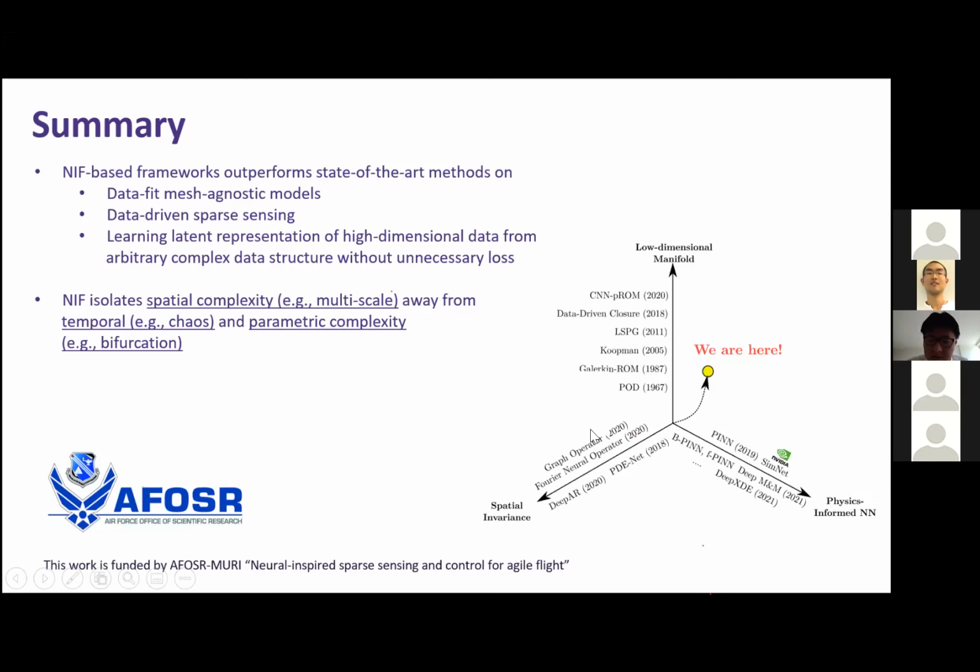There are several other interesting new frameworks, like the graph neural operator framework. As I mentioned before, they also leverage spatial invariance. However, for a neural operator, the major issue is that you really need a square computational domain in order to use the convolution theorem to do the Fourier trick. For example, if you have a triangular domain, you cannot do this at all.